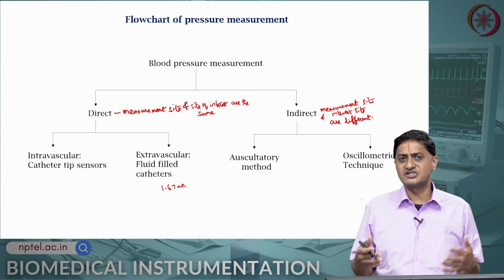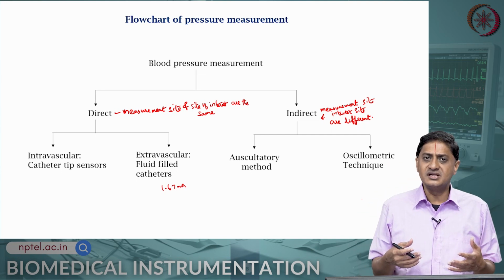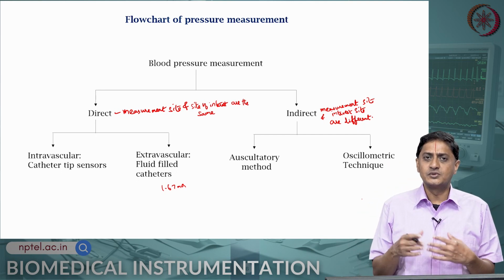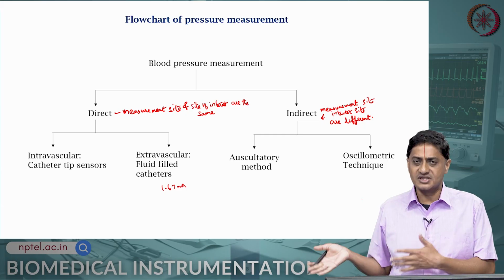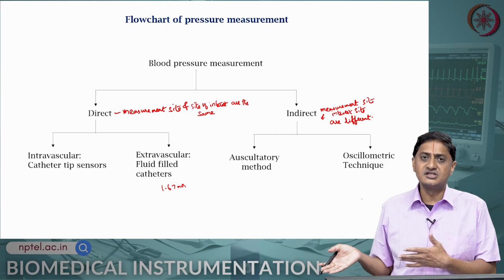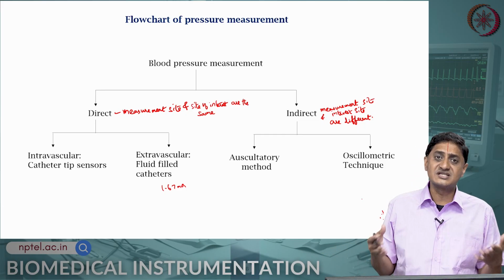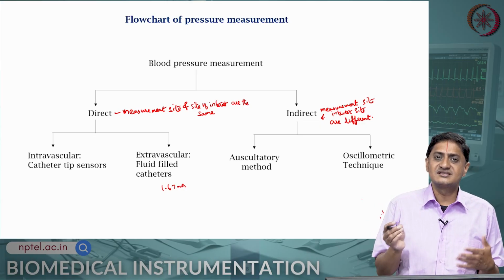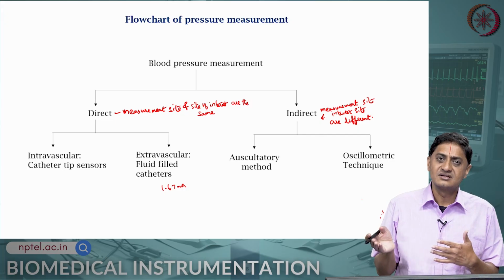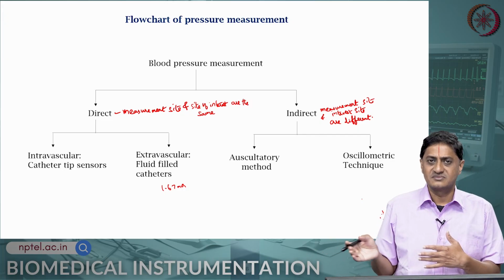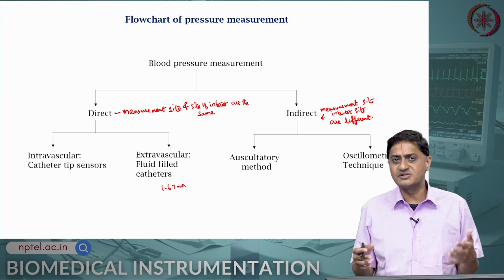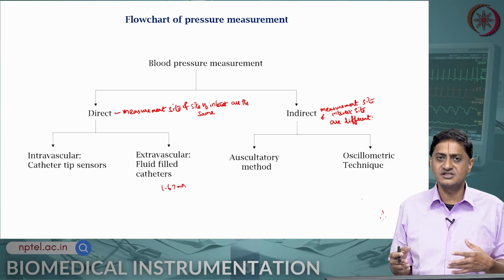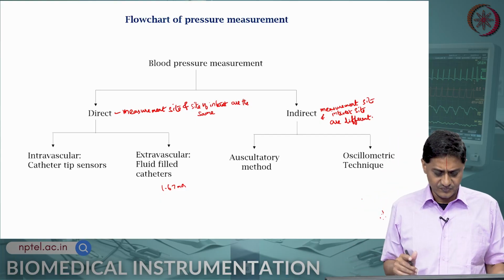For example, if it is a strain gauge, that strain is then converted into resistance, which then outputs a change in the voltage, for example, or if it is a capacitive sensor, then that deflection changes the capacitance, which then outputs a change in the voltage, for example. There are different types of these, and there are advantages and disadvantages to each of these.